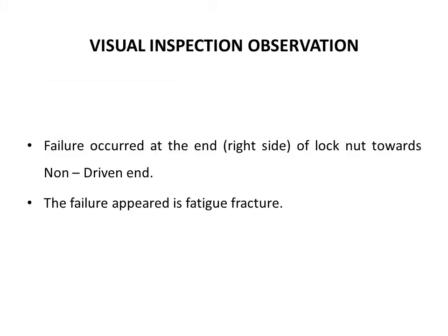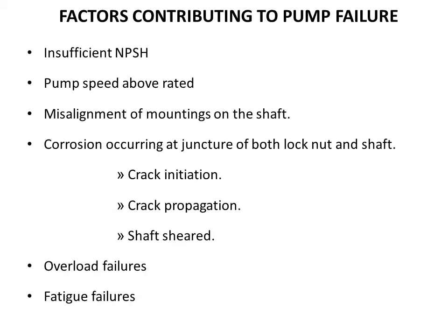Visual inspection observation. Failure occurred at the end of the lock nut towards the non-driven end. The failure appeared is fatigue fracture. Factors contributing to pump failure: insufficient NPSH, pump speed above rated, misalignment of mountings on the shaft, overload failures, fatigue failures.